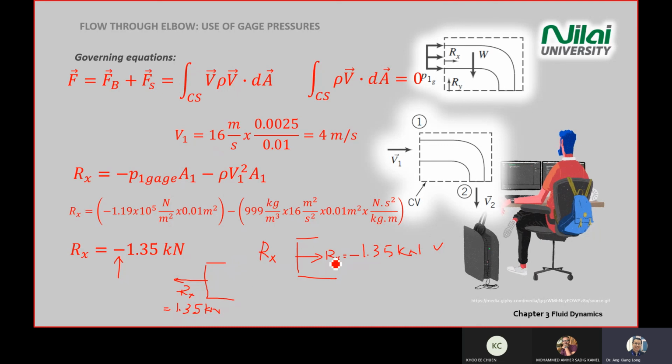Both diagrams have the same meaning. The one on the right is the same as the left diagram here. You only need to understand what the negative means in your answer. Negative means the direction you assumed earlier is wrong. If you draw back the free body diagram with the arrow of the original diagram, you must keep the negative in the answer. However, if you already flipped the direction, remember to take out the negative sign in front.